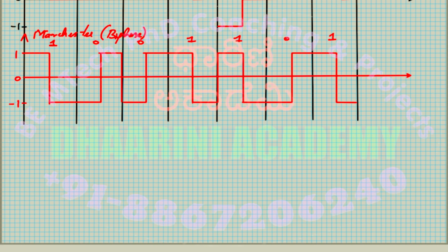Though you say that I have a digital circuit, I'm trying to send zeros and ones, zero zero is a NAND gate or NOR gate, whatever, zero zero is one, etc. When it comes to the actual implementation on the chip, it becomes 3.3 volts and 0.5 volts. You see the difference, right? So one becomes 3.3 volts, the zero becomes 0.5 volts. So actually the level refers to the voltage in the practical case.